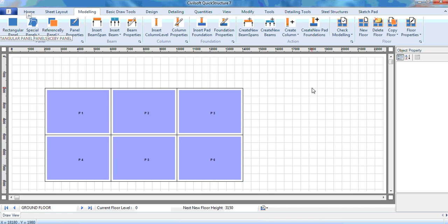Now, once you have created your panel, the next thing is to copy for the subsequent floors. Remember, this is the ground floor. The ground floor is not actually a structural element except if you have the raft beams. But we usually use the ground floor as the starting floor, or whatever is the starting floor, so at the end you can copy the floor to the next level. It's just easier, so you don't go back after doing the first floor to do the ground floor. I mean, it's a little bit clumsy.